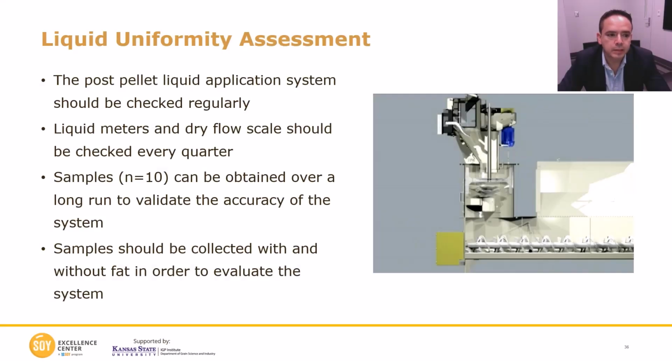The other part that is important is to evaluate liquid uniformity assessments, and the post-pellet liquid application system should be checked regularly. Just like in mixing, you should evaluate the uniformity at least twice a year, and liquid meters and dry flow scales should be checked every quarter.